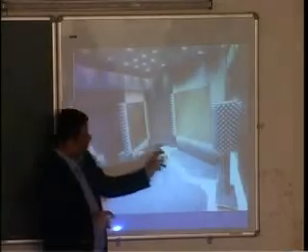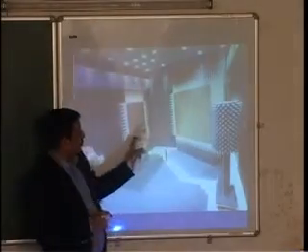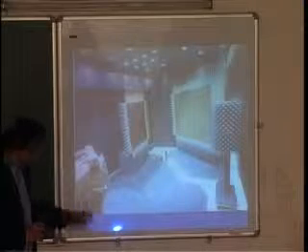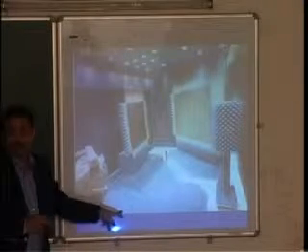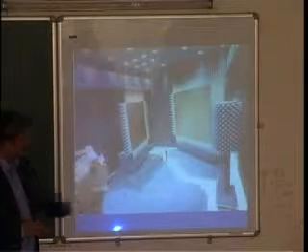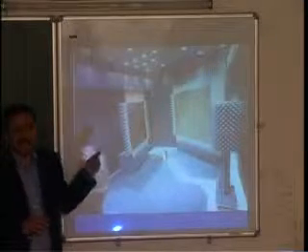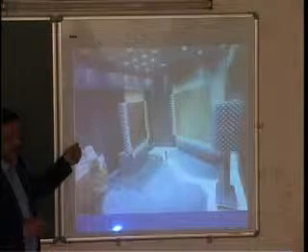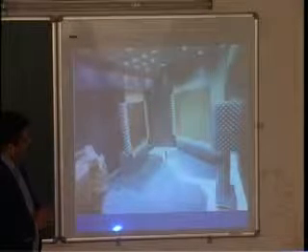So this is nothing but a Cassegrain geometry, where one is a sub-reflector and the other is the main reflector, and we are able to do the measurement. You see, even the wall and the floor are also covered with absorbers. The design of the chamber is done in such a way that the absorbers, depending upon the power which is getting reflected from the different sources, are rated accordingly and kept on the particular wall.